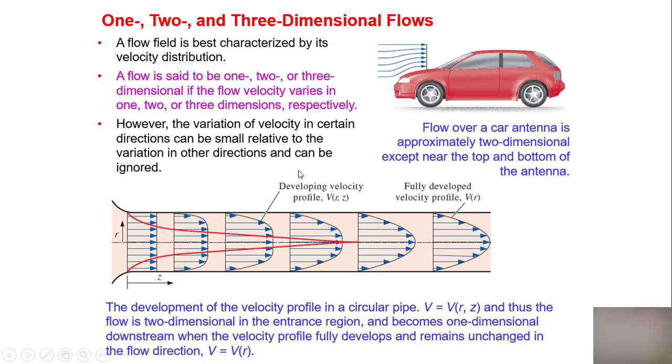These diagrams and graphs show what is known as the velocity profile. We know that the flow will be faster at the center of the pipe and slower as we reach the surfaces. This is due to the first term that we talked about, the no-slip condition, where close to the surfaces the flow is equal to 0, and 0 at the surface itself, but away from the surface the flow increases speed until we reach the maximum speed at the center of the pipe.